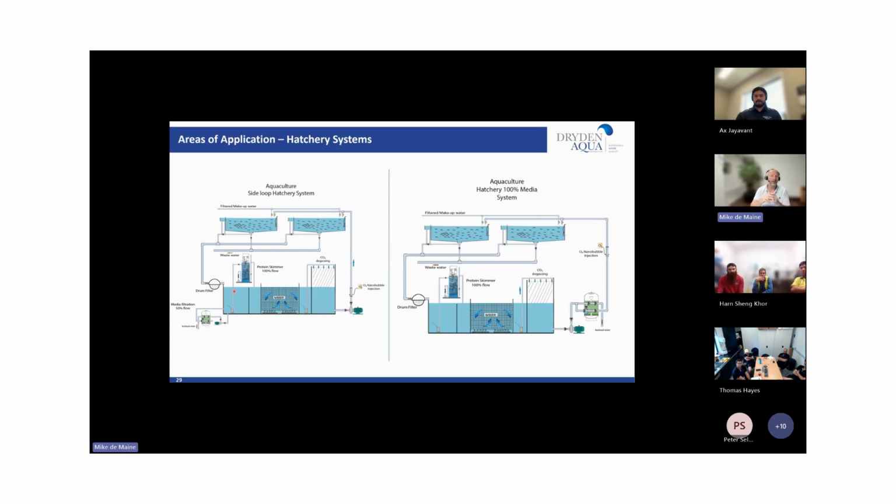Because I can tell you in salmon farms in Scotland, the organic load is so soft there, it very easily gets squeezed through the mesh. So their drum filters need to pretty much be washing down continuously to prevent that from happening, but even still, they get some penetration.